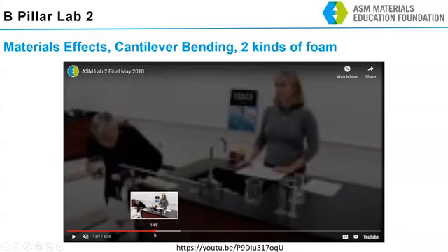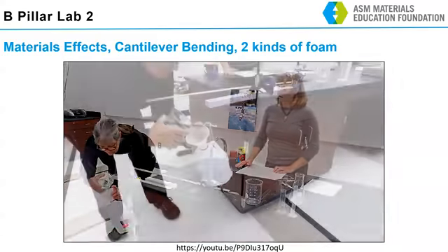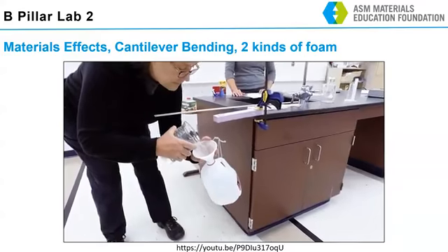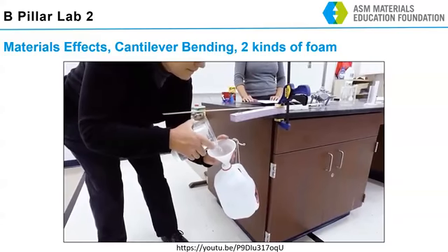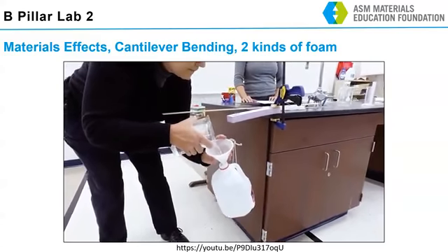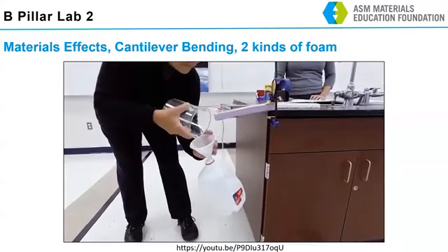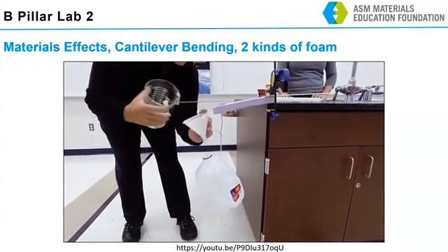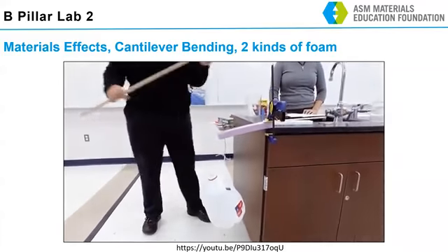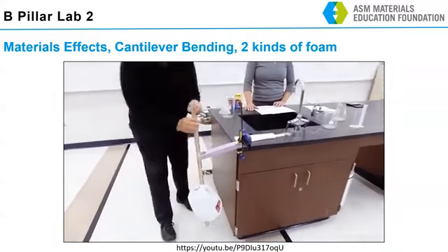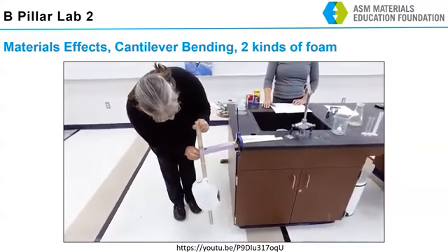Okay. And you would want to have your students incrementally add the water and measure the incremental deflection. And when they plot that, the slope of that plot is going to be related to the stiffness of the beam material. Okay. And if you did this in your classroom, you would probably want a 5-gallon bucket under there to catch your water when things go south. So you can see that's visibly sagged. So that's measurable even in classroom circumstances. I can get the deflection.